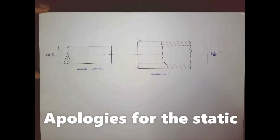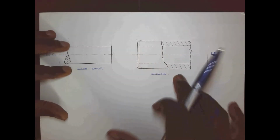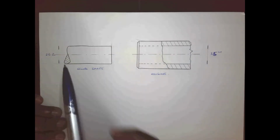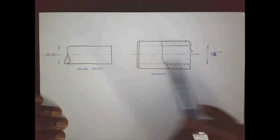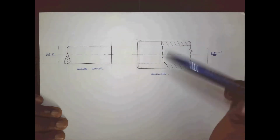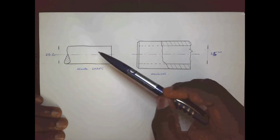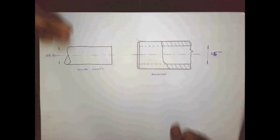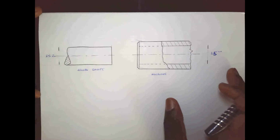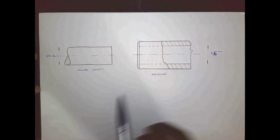Alright folks, let's look at this problem in much more detail. A shaft of 85.2 millimeters needs to be fitted into a housing which has a bore of 85 millimeters. The shaft is slightly larger than the bore in the housing, which means this can be done in two ways. Either the housing is heated for the bore to expand enough to accommodate the shaft, or the shaft is cooled for the diameter to contract to fit into the housing. Whatever is economical. In this instance we're going to look at how the shaft can be shrunk significantly enough to fit into the bore of the housing.